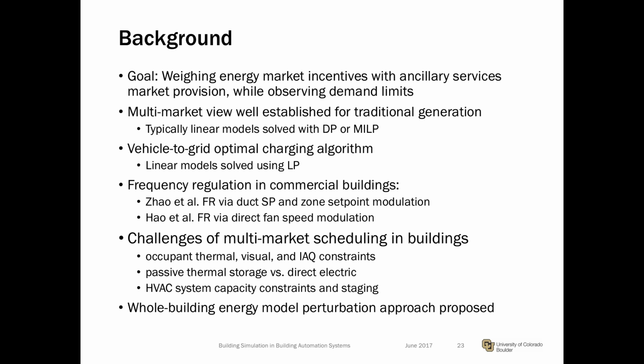However, this multi-market scheduling of buildings does face a few challenges. For one, we need to consider occupant thermal, visual, and air quality constraints. We cannot do just everything we would like to do with buildings. And clearly, building thermal storage is not equal to an electric battery, so it has charge-discharge constraints that we need to consider. And the equipment we utilize, the HVAC equipment, is clearly subject to constraints as well.